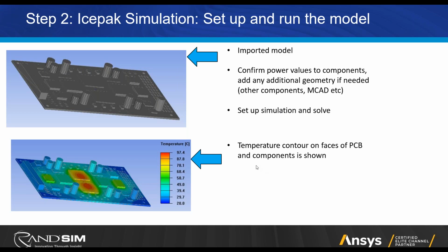For this analysis, we did 2 different temperatures at the extreme ranges of the thermal cycling, which we intend to apply as part of the solder joint fatigue. There'll be more on that later. So once you choose your thermal setup and simulate, you'll see something like this. Now we have a mapping of each point on your PCB and on the components to a specific temperature that's motivated by the power dissipation.